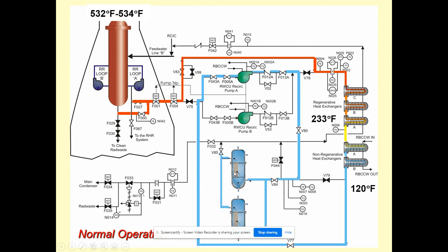And then after it does that, it's going to go through these 2 demineralizers. So we're just getting all the positively and negatively charged ions out of there. And then you can imagine like the sand or the pellets are also going to work as a filter. So if there's any larger debris in there, maybe something the size of a speck of rust, it's going to get stuck on these and not make its way back. So this is a physical filter as well as being an ion removal system.